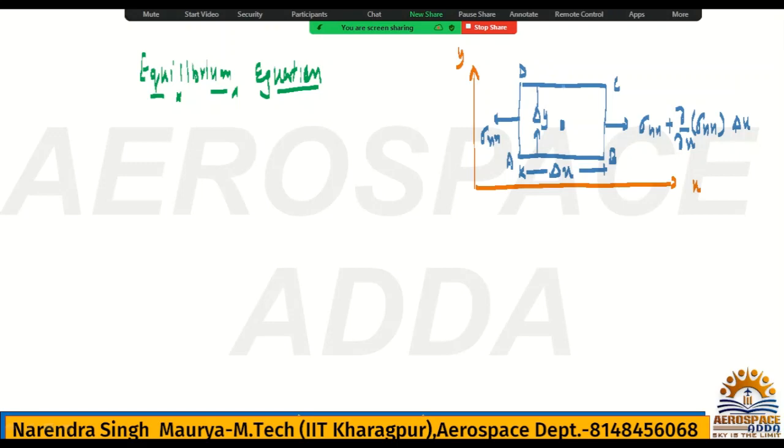Similarly, we will have here this, because it's the y-axis, so this is sigma yy, and obviously here it will be sigma yy plus dou by dou y sigma yy into this vertical length, which is nothing but delta y. So this is the way to write the stress system, and this is the origin, okay. This is the origin or center, you can say.